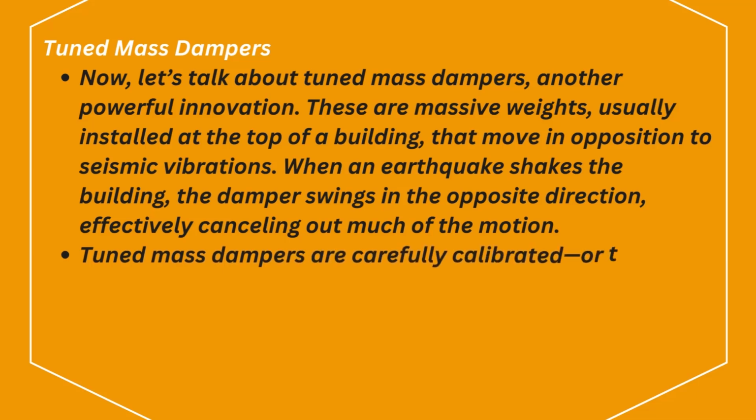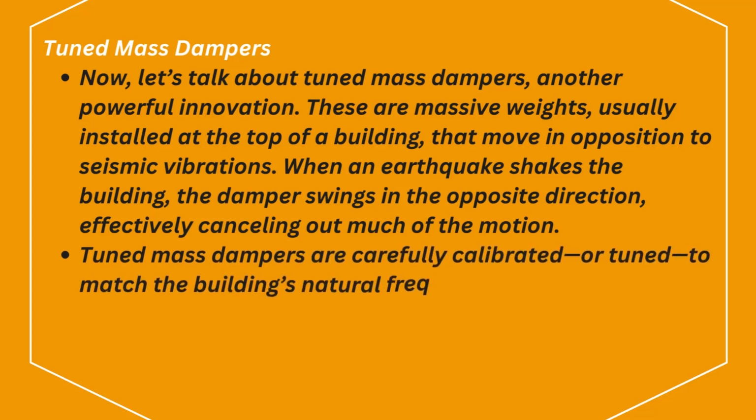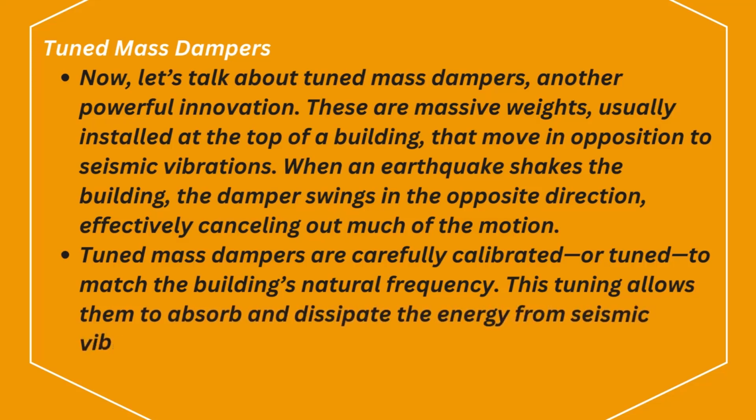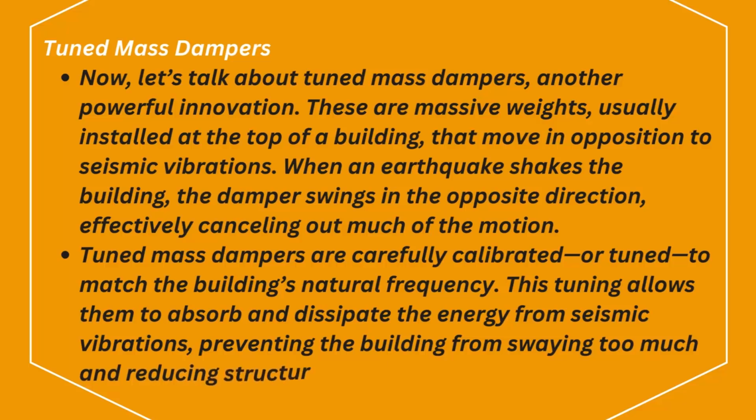Tuned mass dampers are carefully calibrated, or tuned, to match the building's natural frequency. This tuning allows them to absorb and dissipate the energy from seismic vibrations, preventing the building from swaying too much and reducing structural stress.